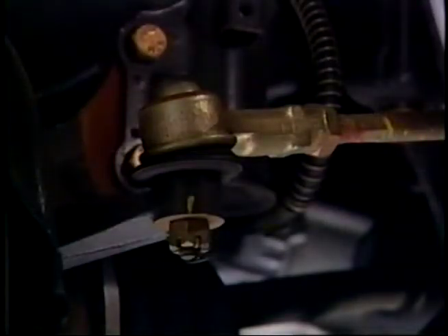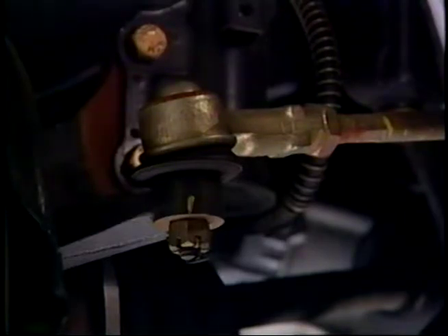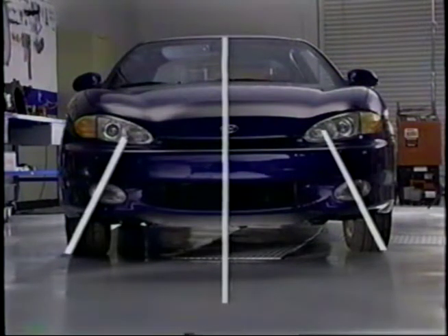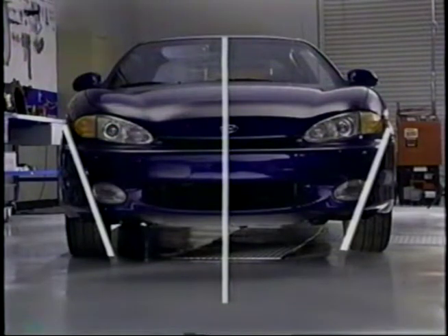Toe is adjusted with the tie rod and adjusters. The steering wheel is also centered using this adjustment. Camber is the relative position of the top of each tire to the vertical center line of the vehicle. Where the top of the tire is closer to the center line than the bottom, the camber is negative. A slight amount of negative camber is usual, as the top of the tires will move out with speed. Excessive negative camber will cause the tires to ride and wear on the inside edge. Positive camber is abnormal and will cause the tires to ride and wear on the outer edge.